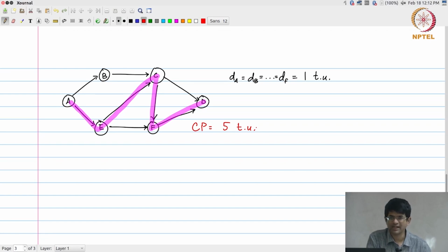Just for reference, what should the iteration period bound of this circuit be? Going back to what we discussed last week, the iteration period bound is the minimum achievable theoretical iteration period. Even in theory, assuming infinite hardware, what is the minimum iteration period that can be achieved for this circuit? 0. There are no loops over here, so there are no feedback loops. This is an example of something that is completely feed forward.